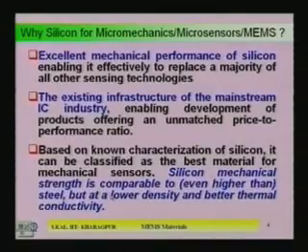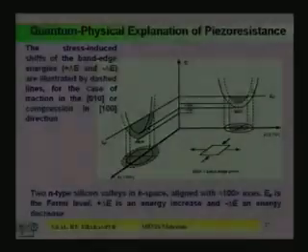Silicon mechanical strength is comparable to, even higher than, steel, but at a lower density and better thermal conductivity. In the last slide I showed you its density is lower than iron and its thermal conductivity is also very high, compared to 1.5 times of that. So, because of that it cannot generate a lot of heat, dissipation is more, and that is advantageous compared to other materials of the traction.